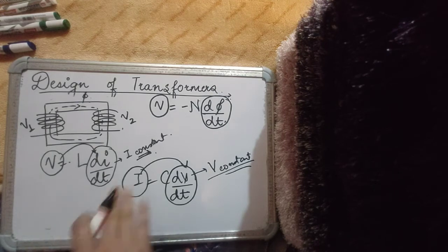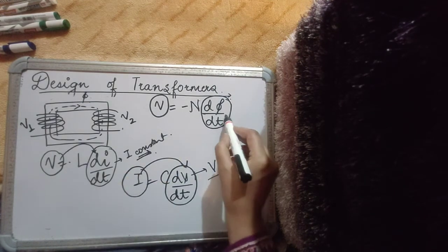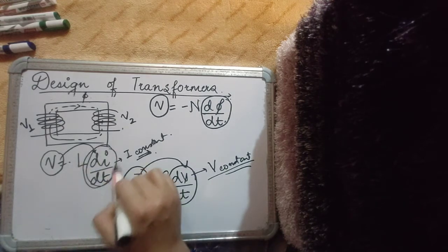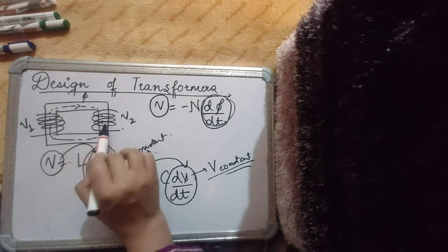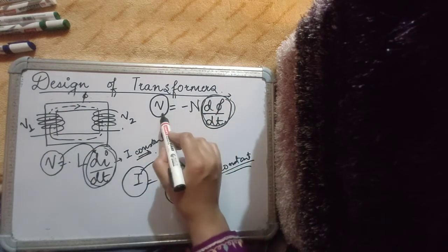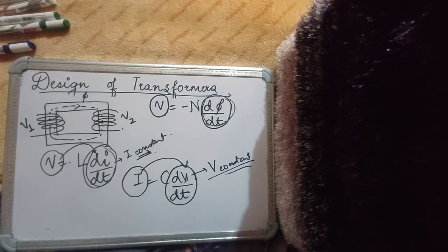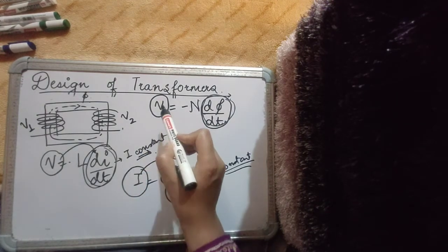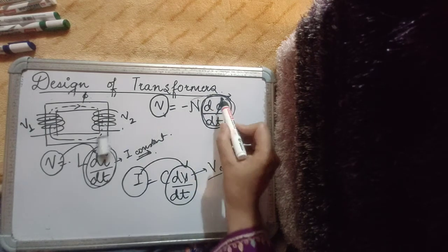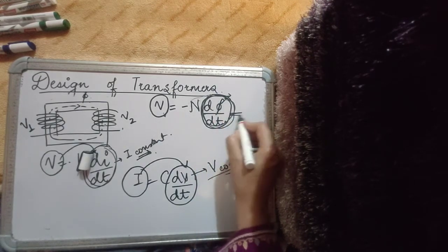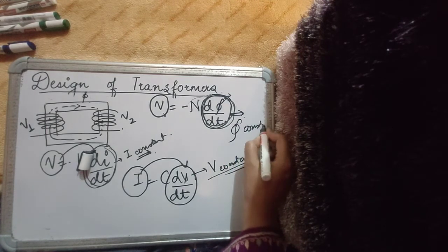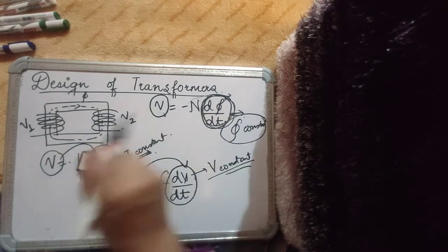Similarly, just the same analogous situation is going on with transformers: transformer windings, which are no longer dealing with just currents but with flux being associated with both windings, they induce EMFs. These windings, which are part of a transformer, induce EMF across them in such a way that the flux across them remains constant. So dφ/dt is minimized. So your flux is constant. That is the operation of a transformer.